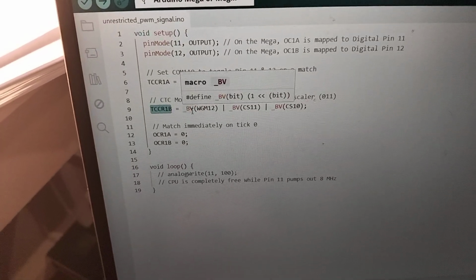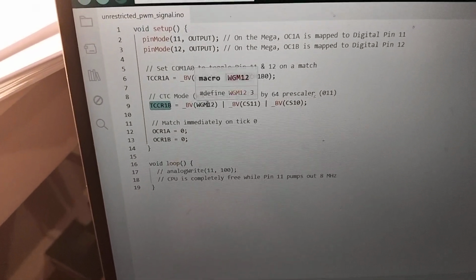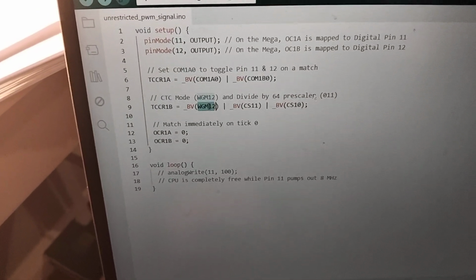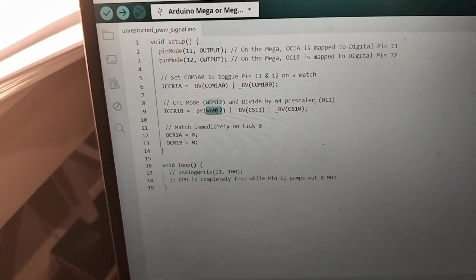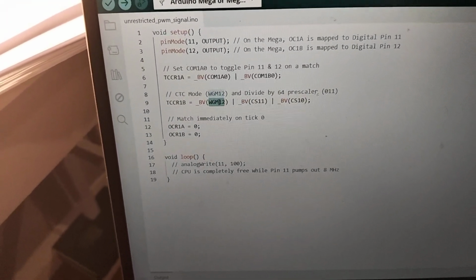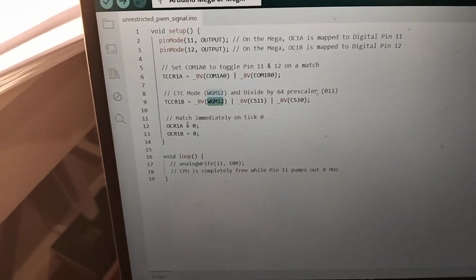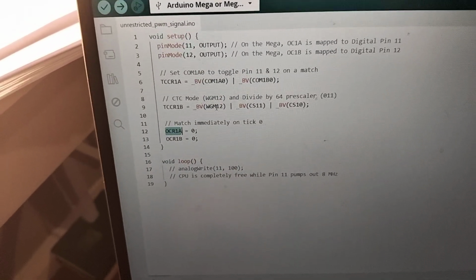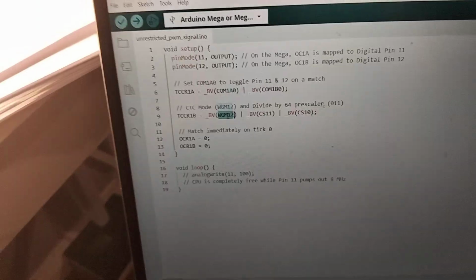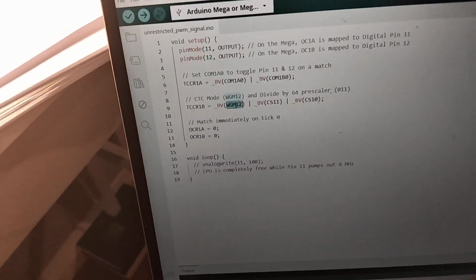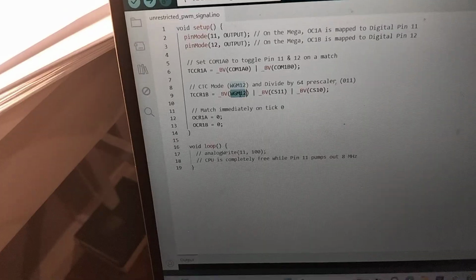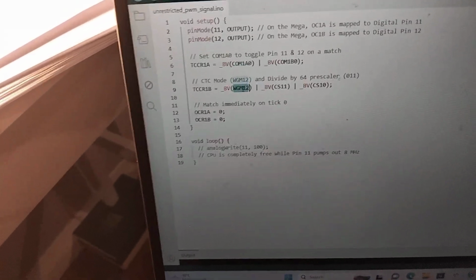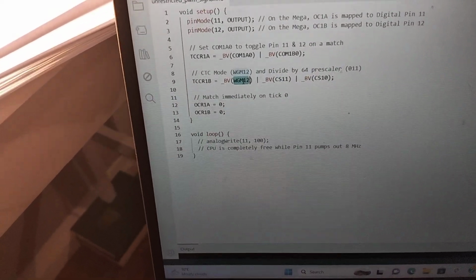In this instance, the 3rd bit, I set that because it determines if the timer should reset if it hits the check register. And so I set that to be true, which means the timer will just stay at 0, because it starts the loop, it hits 0, it checks, and then it resets itself back to 0 immediately,